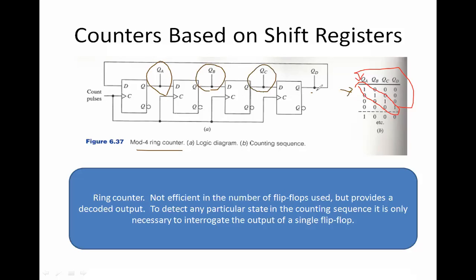Through these access points, you can find out if you're properly getting values at the D flip-flop, the C flip-flop, the B flip-flop, or the A flip-flop. If there is any discrepancy, then we can look at only that particular flip-flop, find out the errors, and start rectifying them. So that's the reason why these points are given. Can I move on?